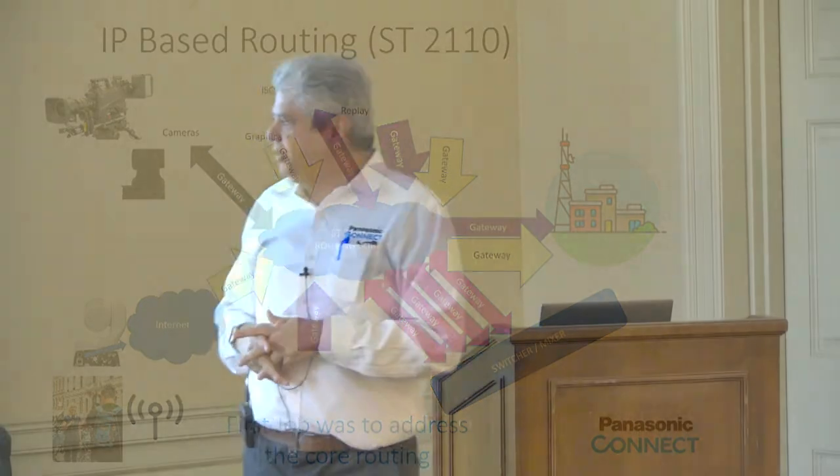So with IP-based routing, the first job is to route the video, because SDI routers were, A, expensive, and B, it was not easy to do routing inexpensively. So with ST 2110, they have to make everything route through the standard network switch. And in order to route the video, they have to make everything talk to each other, and everything can be easily routed through your software-based network managed switch. And that was the biggest challenge ST 2110 has.